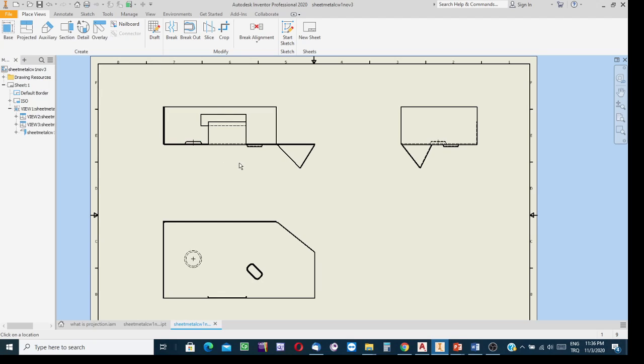Well, start the view creation process, place views, clicking on the base view creation button. Only for sheet metal work, at the development creation stage, we click one more time onto the base view creation button. If the views are not developments but, say, principal views, then it is a must to click on the base view creation button only one time at the beginning. Well, for creating the other views, if you started from the front side view, the projection button is clicked by the software in the background.